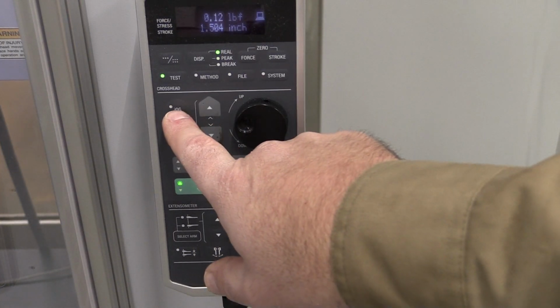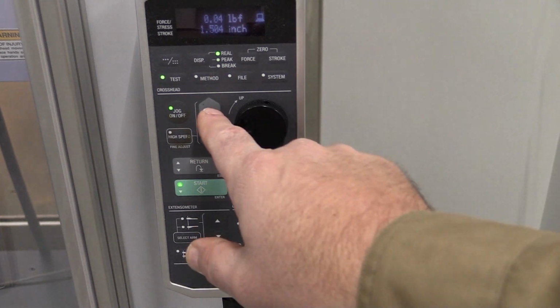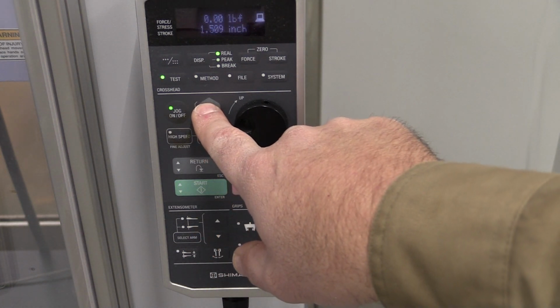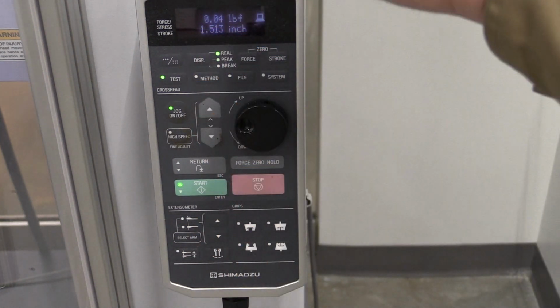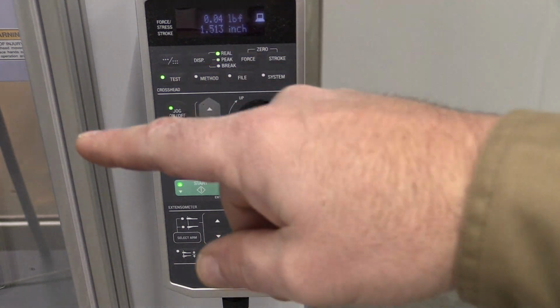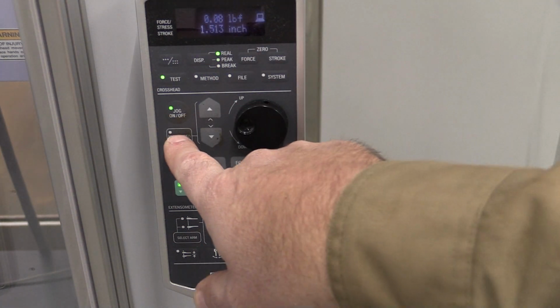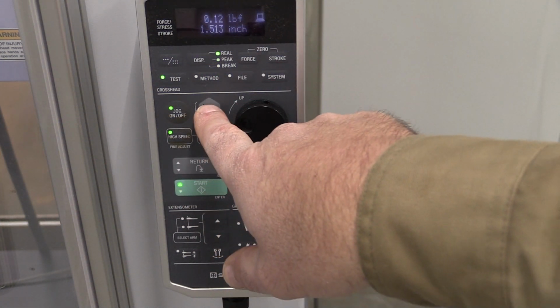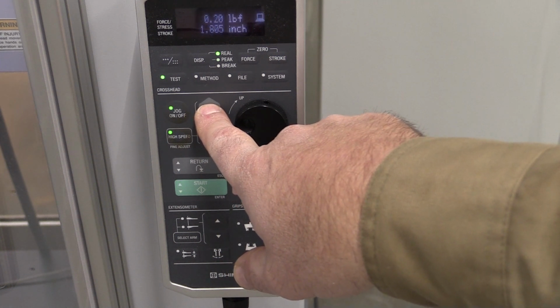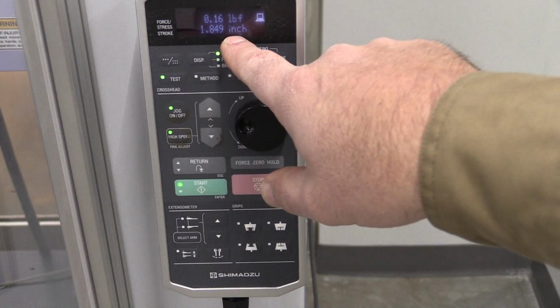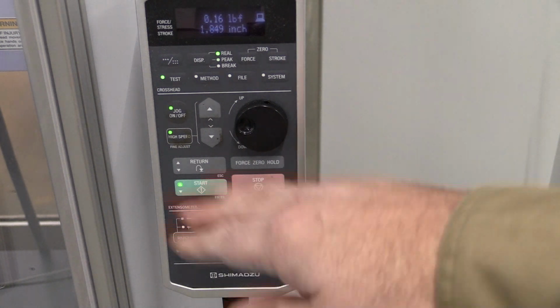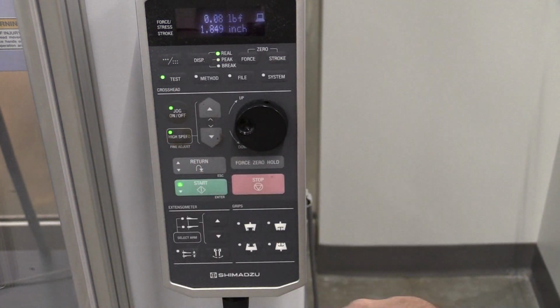So we can come in here and hit hand jog, and this is going to be in the slow mode. If I raise up, you can see it's moving, and that's going in the positive. So you want to make sure you're going in the right direction so you don't crash the machine over there. I can move high speed, and it's going to come up at a much faster rate, a lot more displacement. So you've got to really be careful with that. It's beeping because it lets us know we're in high speed mode.